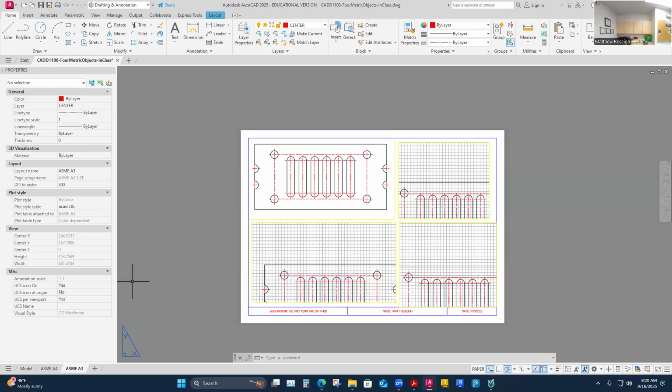Now, then pull it and just see what I did. I actually had a center line across there. Maybe go to your construction line. I drew, oh, you need to trim that out. There is no center line that one has. Now it will naturally have a center. You don't even need a line. I'll snap it across. That on your center layer, you can push it to construction.